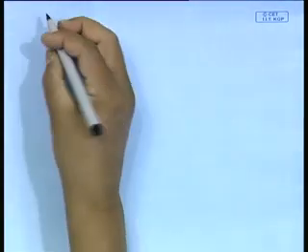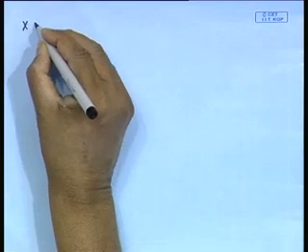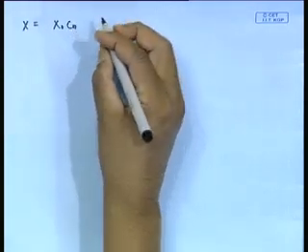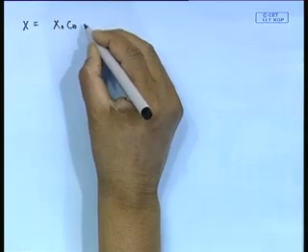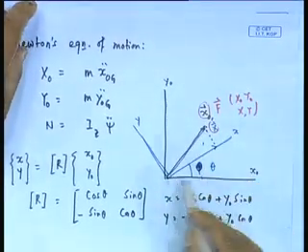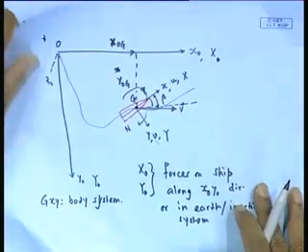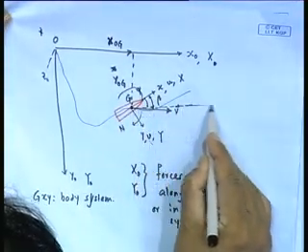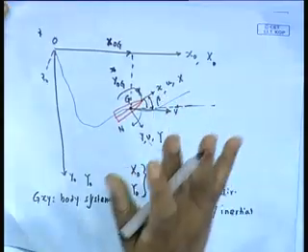Now I will just rewrite that, because we need to do this. So we have x equal to x 0. Let me now put psi instead of theta. This theta was a general coordinate transformation, but in our case, as you know from the definition of the diagram, psi is the angle between the horizontal line and the heading, not beta.